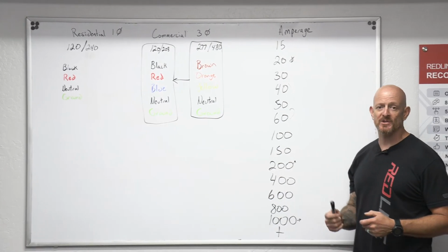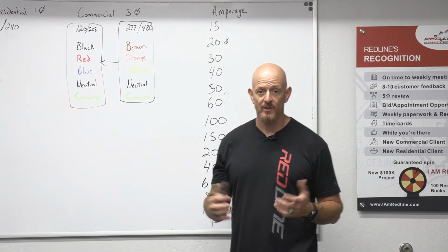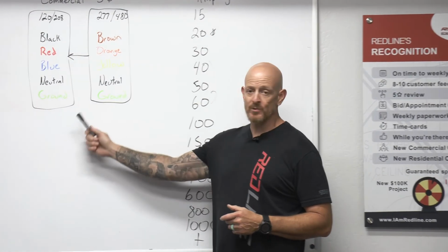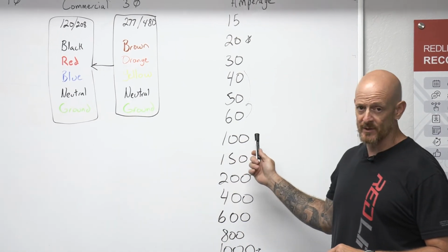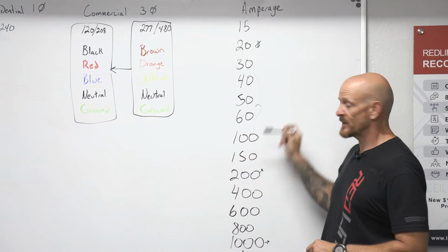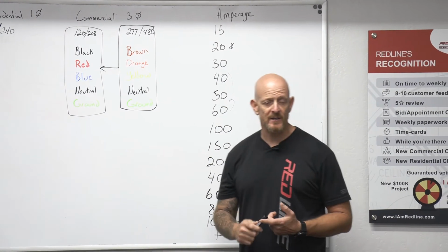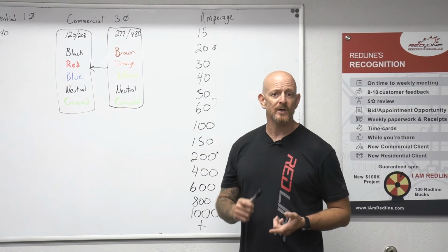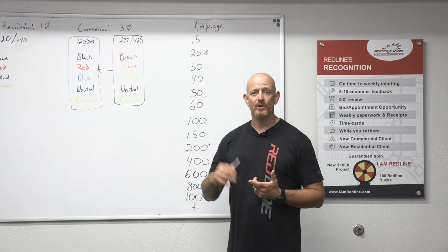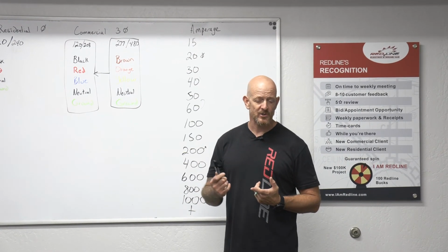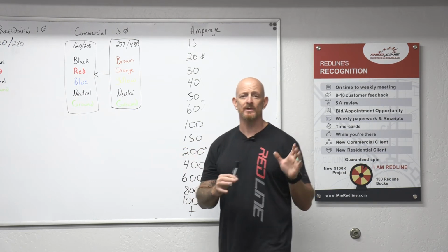Amperage is what determines the wire size. So if you have a piece of equipment that needs a 50 amp circuit, it doesn't matter if it's 120, 208, 277/480, it doesn't matter. 50 amps is what we're going to size that wire. And depending on the application, typically we see a number 8 gauge there. But you're going to want to look in your NEC code book, your National Electric Code book, in Chapter 3, Article 310. The amperage varies on temperature, the raceway that you're using, what type of wire. So you're going to want to find out exactly what the scenario is to determine that wire size.